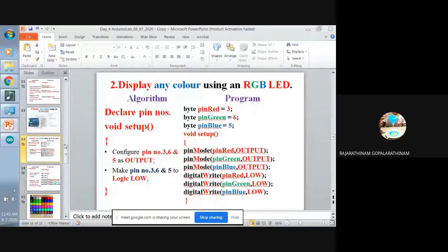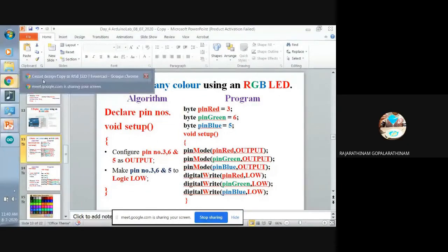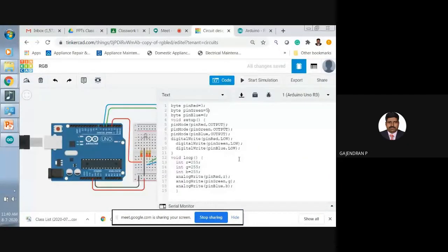See, this is our study. Sir, Marian asks why black is not visible? Marian, actually, if I'm giving all logic as 0, 0, 0, the LED won't glow. At that condition, after the LED, you will have some multiple filters in your display system. At that time, no glow means your display will appear as black. Here we don't have any filter, we are seeing the LED immediately. There they keep some more layers to get the black color appearance.